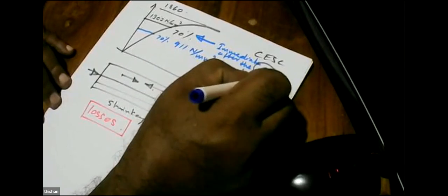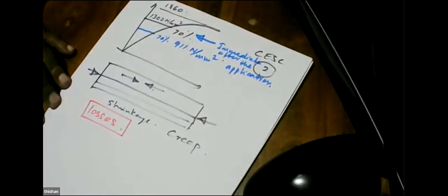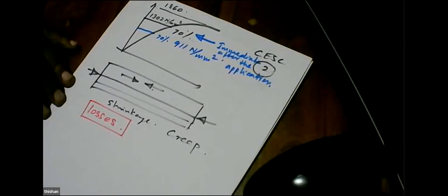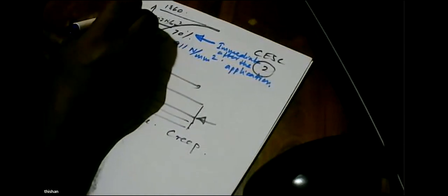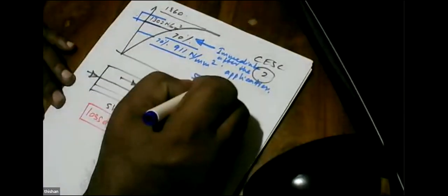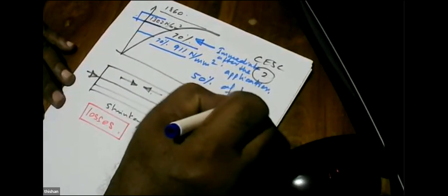As soon as you apply the stress or transfer the stress, if the member does not fail, the chances of it failing later would be much less, because when you are transferring, we are at this level. When you are using it, you are at a much lower stress, around 50% of breaking strength.